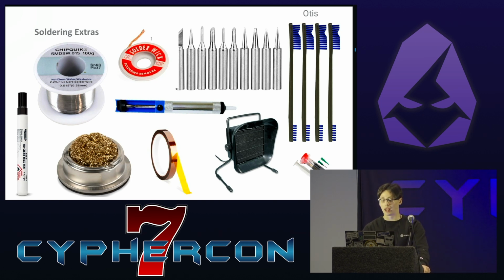This tape is a type of tape, I think the brand name is Kapton tape, but it's very thermally resistive. So if you have areas that you're trying not to burn or trying not to have desoldered, Kapton tape can help to mask off those areas so you don't hit components you're not trying to.